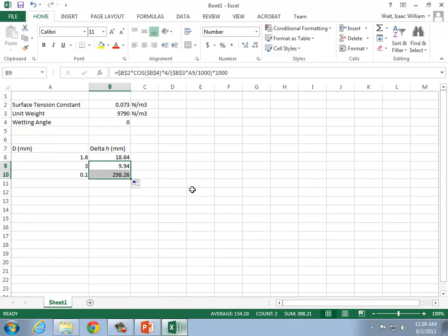And the same is true not just of sand, but of clay, that there's a distribution of soil particles. It's true in gravel, that in a natural system there will be small pieces of gravel, there will be large pieces of gravel. So here we have all these different soil grains that are packed together. Now the water table means that beneath this level, all of those little spaces, the gaps between soil grains, are full of water.